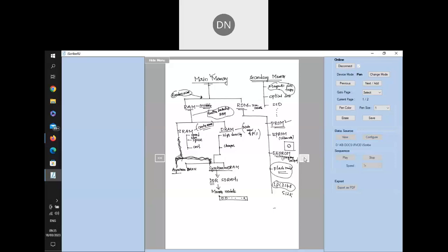The only thing is there's a small battery associated with the memory. Sometimes it is present inside and works for 10 years. Sometimes the battery is present outside. So as soon as the power is switched off, the contents of the RAM will not disappear. It will be there itself. Why is it required? For example, date, time, some passwords. This is information we don't want to disappear even when switched off. But at the same time, you're supposed to modify it at runtime. I cannot use a ROM for this because ROM means it's a fixed, one-time program.